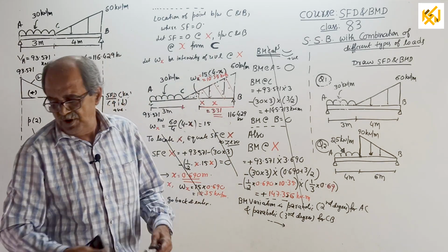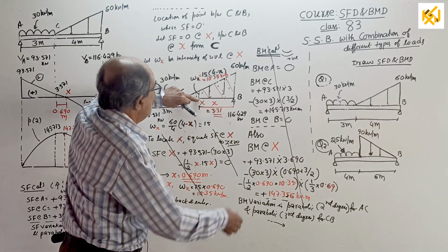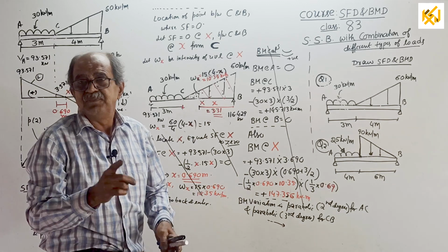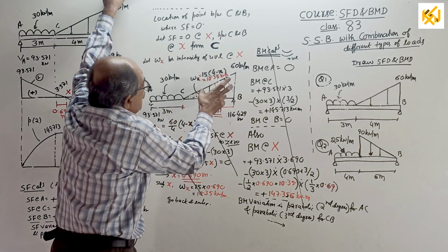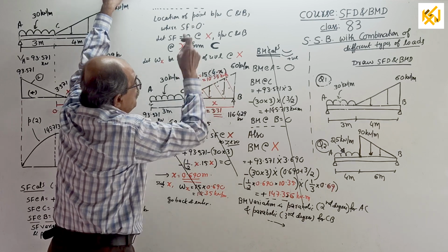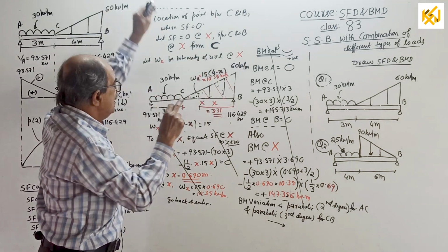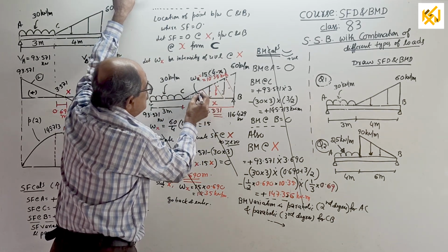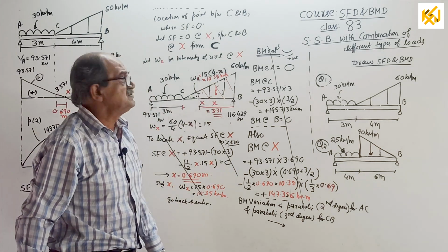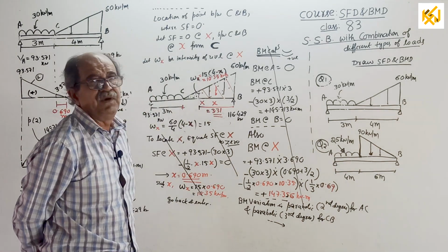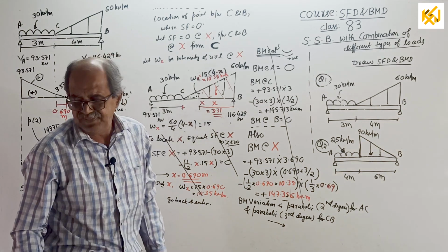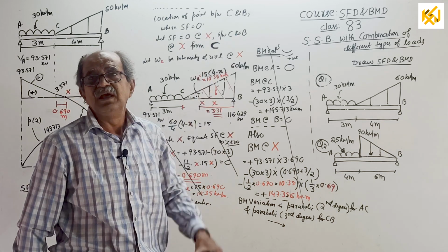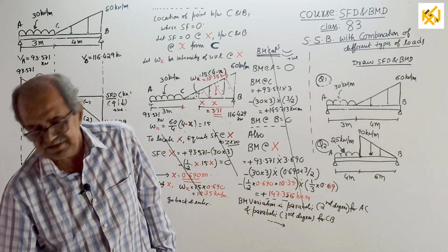Start. Bending moment calculation. BM here equals plus 116.429 into 3.31, that is positive bending moment, sagging, minus the moment of this load: 10.35 plus 60 divided by 2 into 3.31 is the total load. It will pass somewhere here, into this distance, which is 10.35 plus twice of 60 divided by 10.35 plus 60 into 3.31 by 3. I will not calculate. It will come 147.356 kilonewton meter.